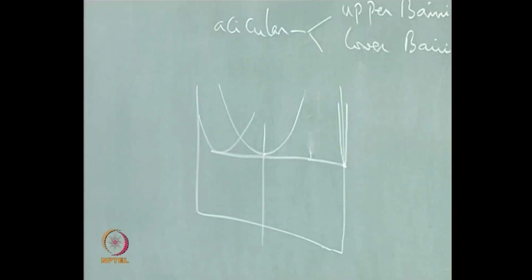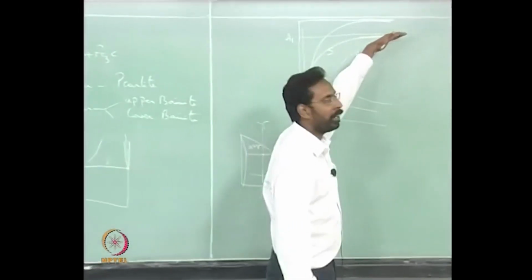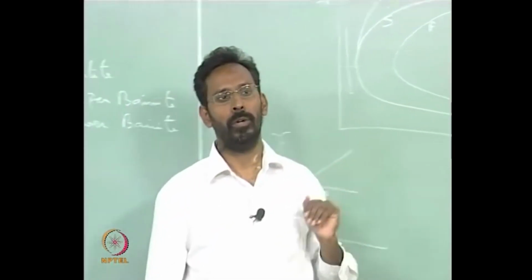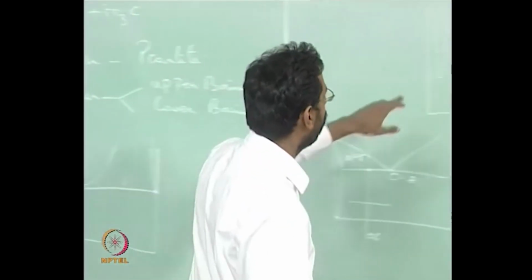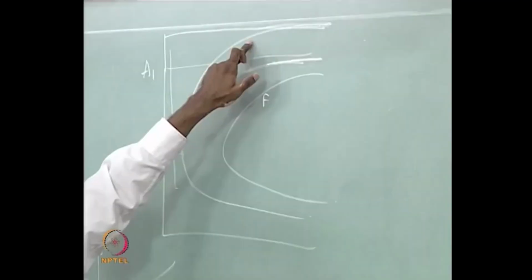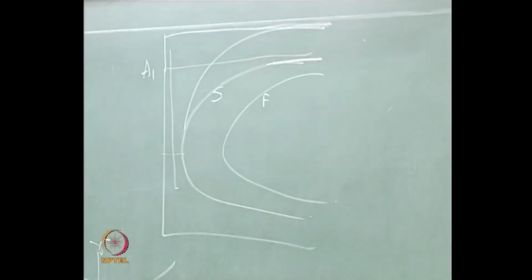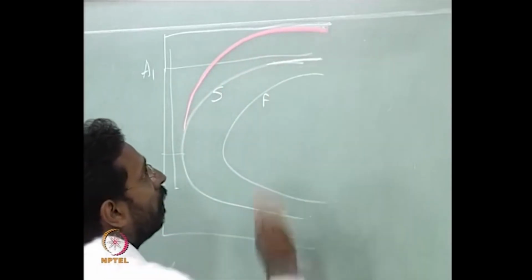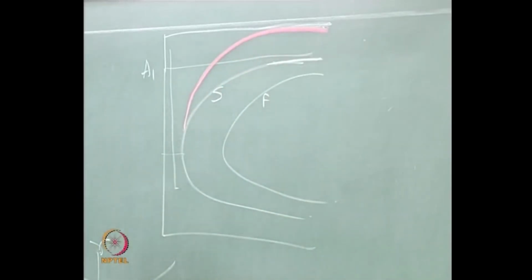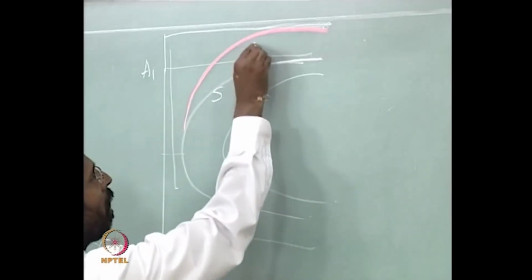So, in principle there is no transformation possible, and that is indicated by the TTT diagram going parallel to the transformation temperature. This is true for this particular line which we have drawn. This indicates the formation of alpha from the gamma as you cool, the proeutectoid phase in this particular case. So, this is gamma plus alpha.